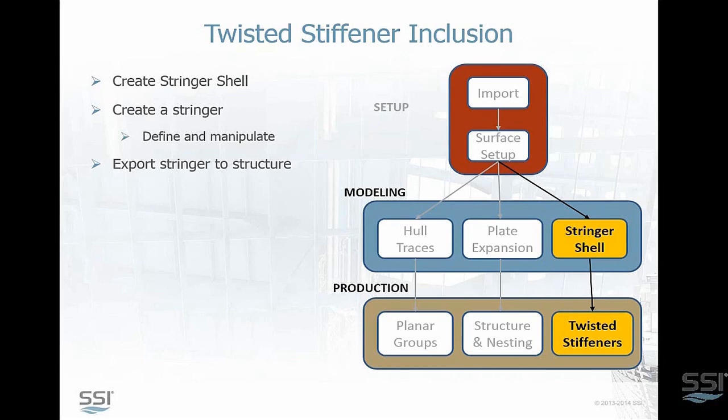in the rest of ShipConstructor, because we'll go back to hull, we'll modify the stringer in hull, and we'll show how that modification of the stringer immediately impacts this twisted stiffener. And then we will also show how this twisted stiffener integrates smoothly with previously modeled parts.